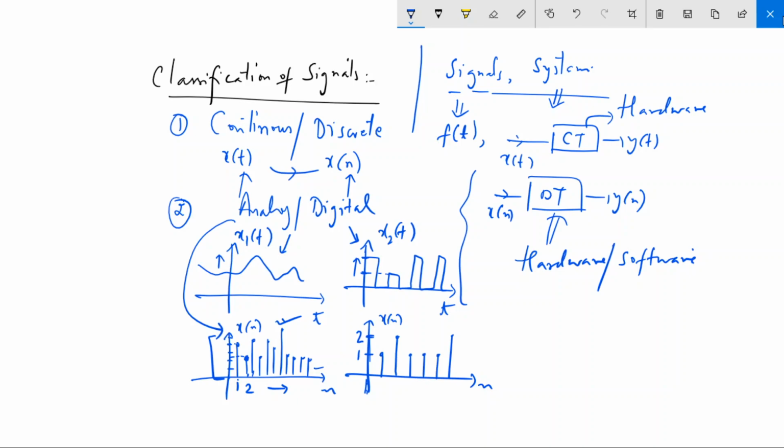So if it is suppose a 4-bit coder, it means each level is represented by 4 bits. So you can have 2 to the power 4, that is 16 levels. So if it is level 0, voltage 0, it will be represented by 0 0 0 0, then 0 0 0 1, and so on, up to finally 1 1 1 1. It means output of that coder will be nothing but a series of binary numbers. For every sample you get a 4-bit code.